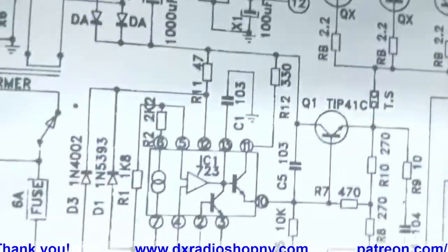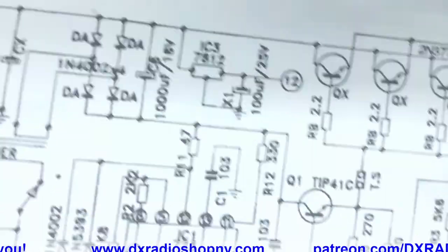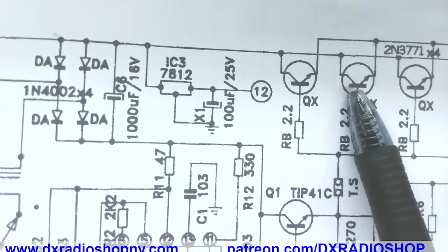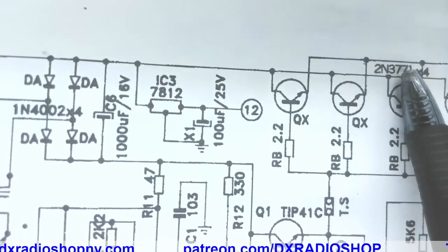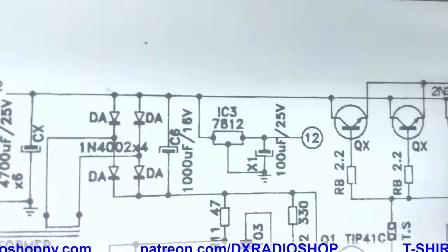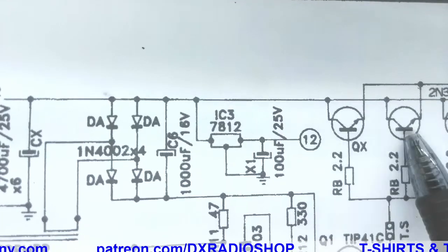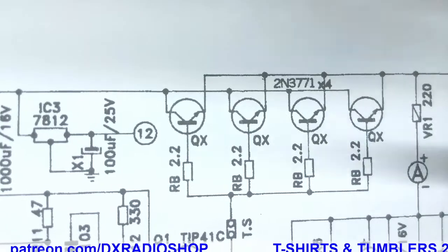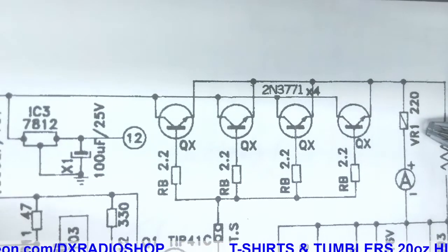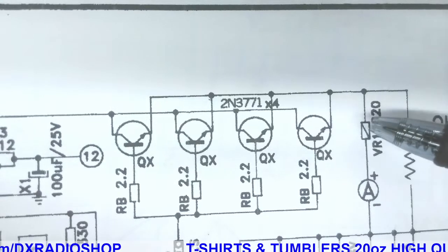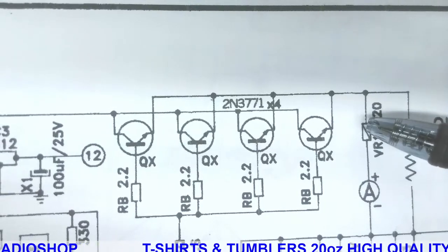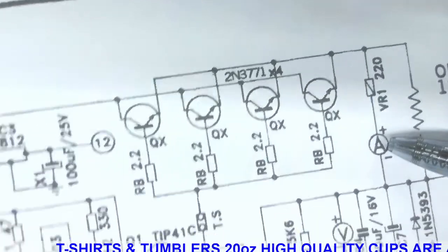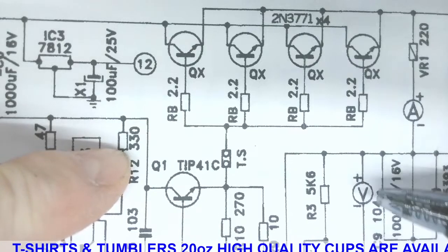Okay, so a lot of these we just discussed, right? You guys can see most of these right now on a print. These are your transistors. These are also known as regulators. With that number, I can justify it as being a regulator. But these are transistor symbols. Okay. Right here, remember the little line I told you? There's a line inside the box, and it says VR1. That is a variable resistor. I forgot to put down meters. Actually, right here is a meter. A is for current. Another meter. V for voltage.